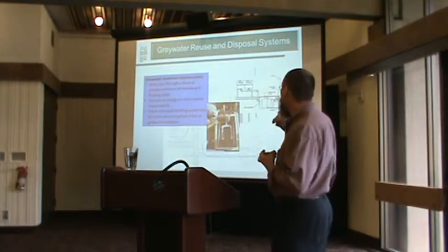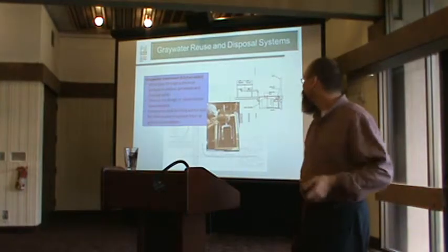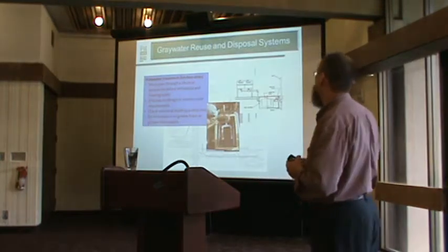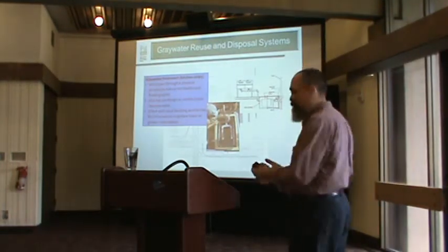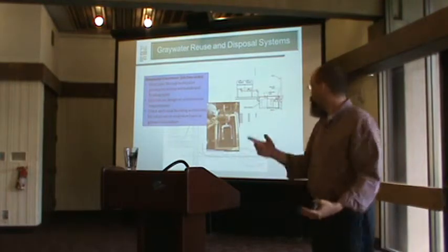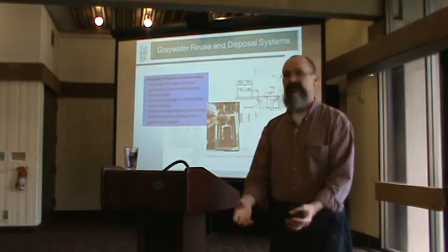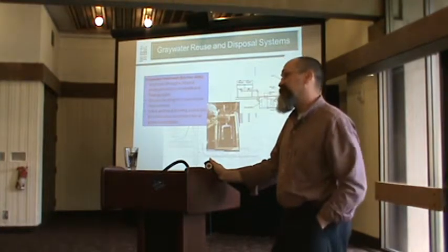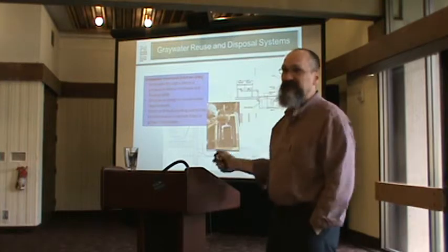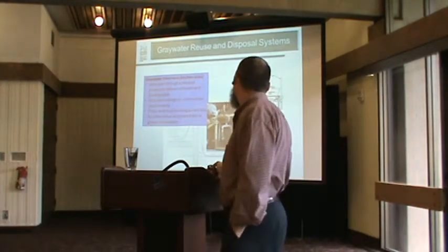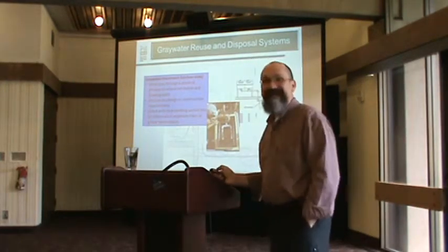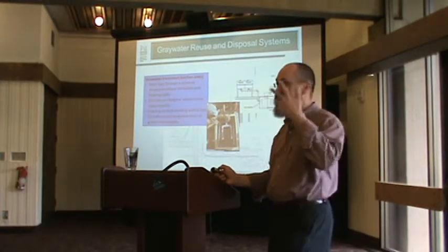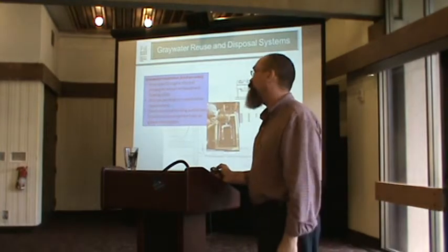On the other one, and this came from the Graywater Action website, is a little mulch box that somebody had put in the backyard, and so the gray water flows into this sort of box, and then it spills over from the pipes in through these wood chips, and that's the way that they do the filtration. So it can be a do-it-yourself sort of system. I think that's going to be nasty to clean out, so I personally wouldn't go that way either. But a sand filter, I mean, there are going to be various ways to do this. So really, as a designer, you think about it. You figure out what's going to work the best.